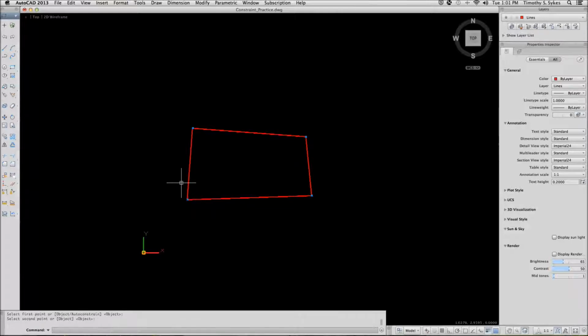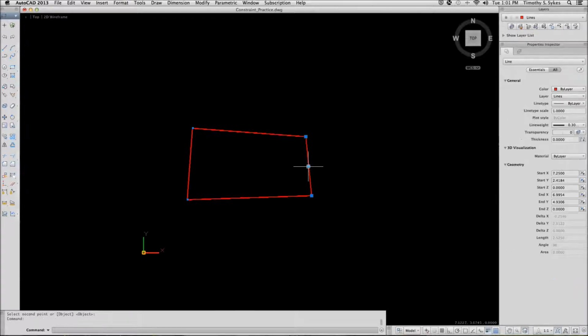Like so. Now, if I go to move the same line as I did once before, notice that the lines remain attached. As I move the one line, AutoCAD automatically stretches the other lines to maintain that connection. Okay, we'll escape out of that.